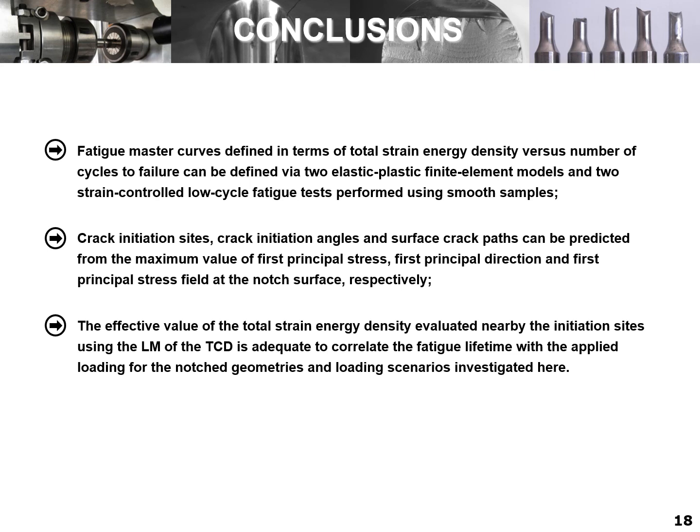Crack initiation sites, crack initiation angles, and surface crack paths can be predicted from the maximum value of first principal stress, first principal direction, and first principal stress field at the notch surface, respectively. The effective value of the total strain energy density evaluated nearby the initiation sites using the line method of the TCD is adequate to correlate the fatigue lifetime with the applied loading for the notched geometries and loading scenarios investigated here.